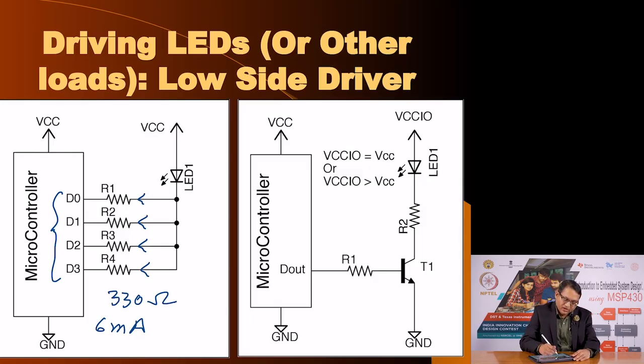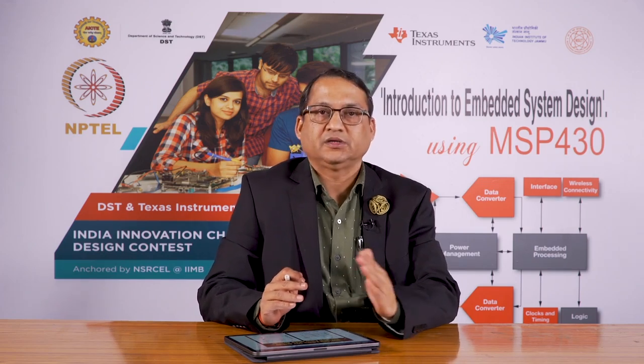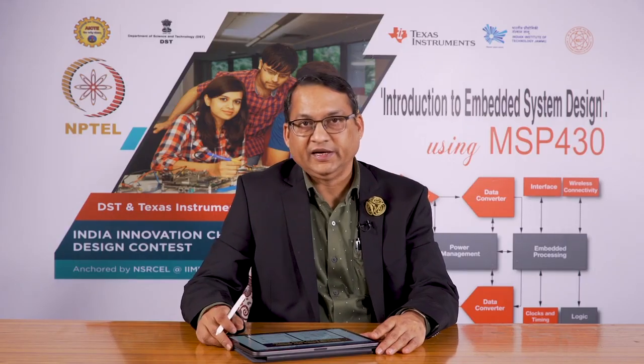what if you turned only D0 equal to 0 and D1, D2 and D3 are set to logic 1? You will see that the intensity of the LED will go from minimum to maximum, and you can actually control the intensity, not just in a binary way, 0 and 1, LED on or LED off. You can have various levels of intensity in the LED.